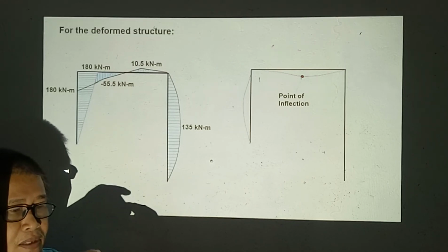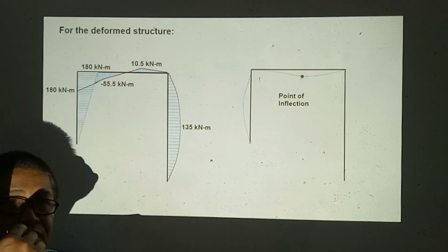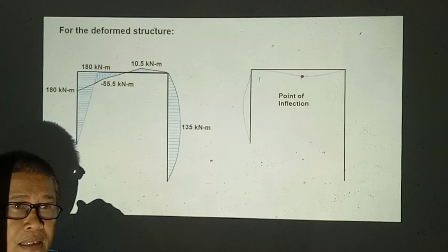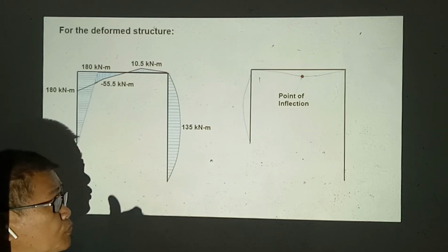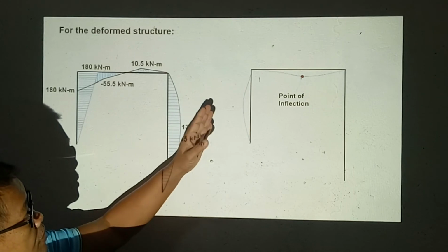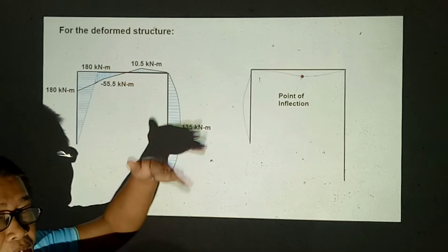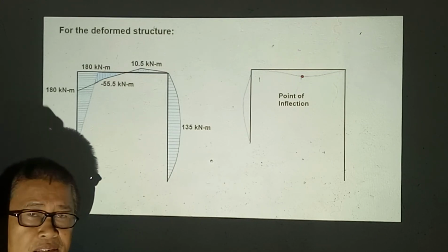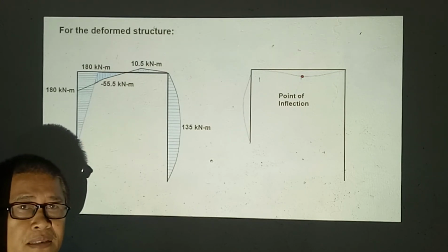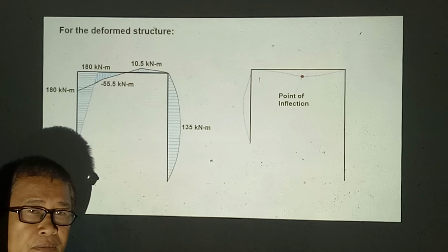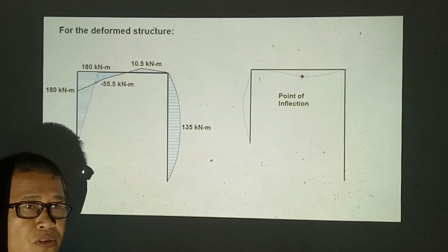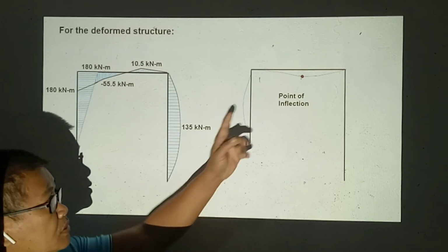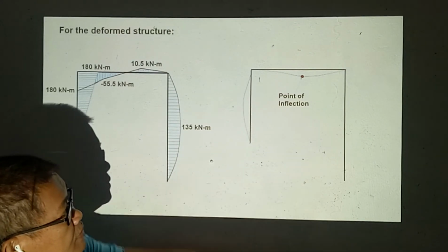So we can make the splices, or in pouring of concrete beams, we can make the schedule of pouring so that if possible it could be stopped if there are any eventualities of stopping of pouring due to heavy rains, or maybe some events that might not allow the continuous pouring of concrete. We can stop the pouring at the point of inflection, in this case, for the